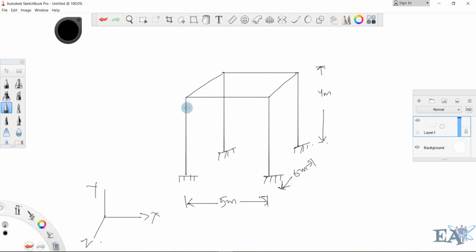Here we only have columns and the frames. We will not have any slab over here because drawing and designing a slab is very complex in STAAD Pro, and while applying the load we don't need the slab at all. That is why we will not be modeling the slab in this structure as well as in the building. I will do a different chapter that will incorporate only the slab portion. Right now, the slab will be omitted. It will not make any difference to the design of our structural members. Now let us model this structure in STAAD Pro. So let us go to STAAD Pro.